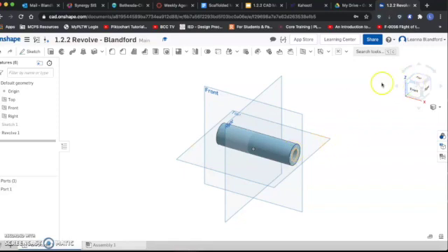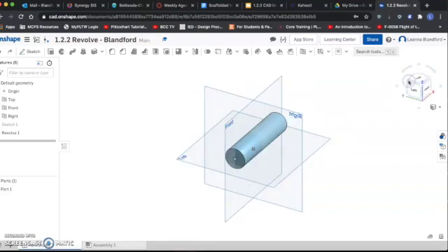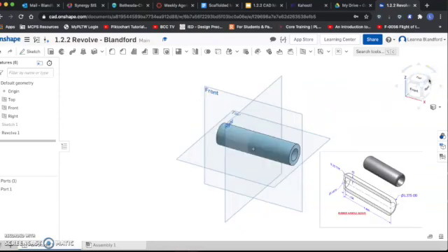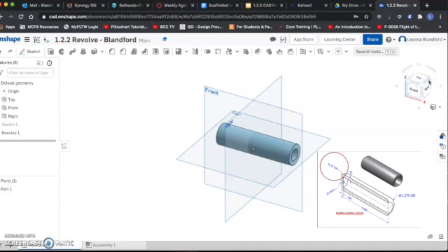So you'll see we have a large opening here, but if we rotate over here, we have the smaller opening just like you can see on slide 5. Now, something that we are missing is the fillet that has to go on these edges to give it those curved surfaces. You'll notice on slide 5 that there is an R.25 TYP. That means the radius of those fillet edges is 0.25 inches, and that's typical for all of the fillets.